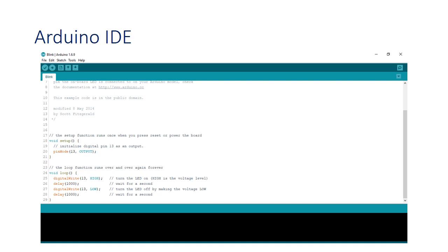Then here we can say delay 1000. Delay 1000 means a total delay of 1 second. Then below here we can say digitalWrite 13 LOW. So we can say digitalWrite is used to set the status of pin number 13 as low and keep it low for 1 second. And again these 4 lines are repeated. So we can say this is an infinite loop. And the task which we have to execute only one time is mostly done in the setup function.